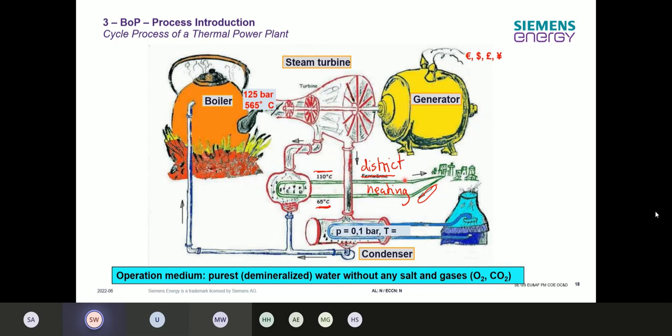And with the district heating, the prices are more or less stable or can get increased, and you're losing a little bit from the electrical part because you're taking steam out, but you can then send megawatt thermal, which you don't need to send through the condenser. So overall, the efficiency of the power plant is increasing. And this can go up to 80, 90% when you look at the amount you're getting in and what you're getting out. So for the power plant owner, it's highly beneficial.